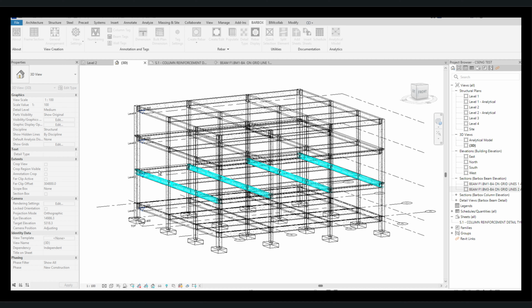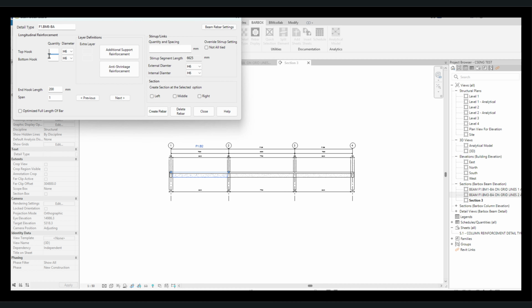Now I'll do a similar one. Here I'm going to go through the rudimentary reinforcement creation by selecting create rebar from the button. Then I'll populate. The population is a bit different; the inputs are different. So I'll do this and set all my stirrup parameters and create.